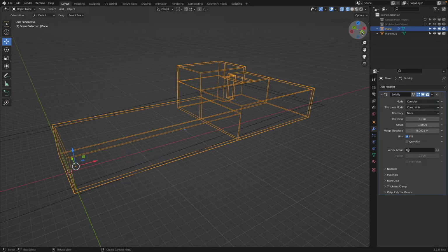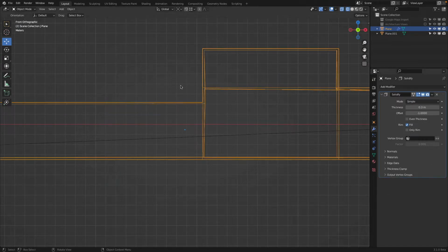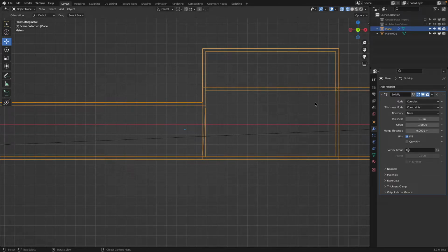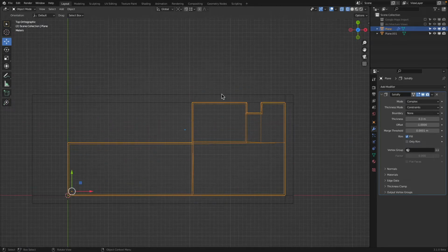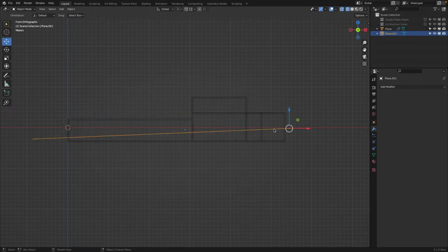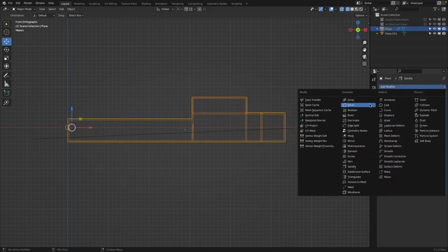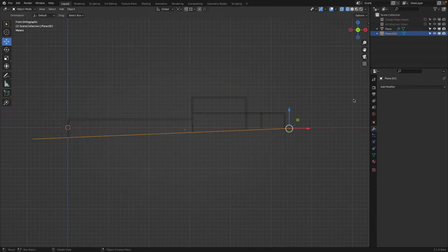Complex. Complex means the software will try to make actually these edges nice and clean. You see this is slightly angled. The shelling command is quite labor intensive in terms of calculation. So this way we make sure that the quality is good. Now this line we created, we would like to use to do a cut. So we do a Boolean cut, difference, and cut this line there. This one here maybe I call ground trim.